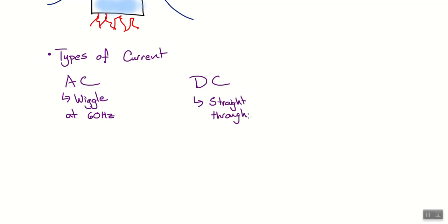If I have a high enough voltage to push the electricity from the power plant to here, do I need that same voltage in the wall? No, it's going to explode anything that I plug into it because we don't have wires that are this thick to move electricity throughout our house. There's an issue. We need to up the voltage when it leaves the power plant, then we need to bring it back down when it gets here.